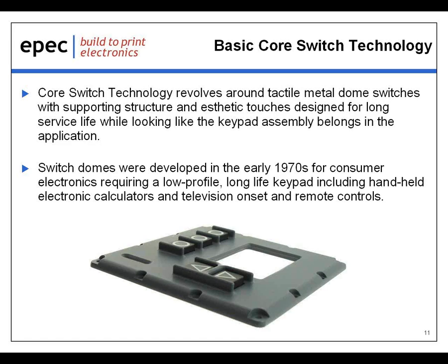Tactile metal domes are available from several specialized metal stamping suppliers, but not all tactile domes are created equal or work equally well. Worse yet, some unskilled designers commonly misapply tactile dome switches in keypads, thinking that the dome switches are just another component with no interaction to other parts. Consequently, too many suppliers in our industry do not produce high reliability keyboards because they just don't understand the engineering behind them.